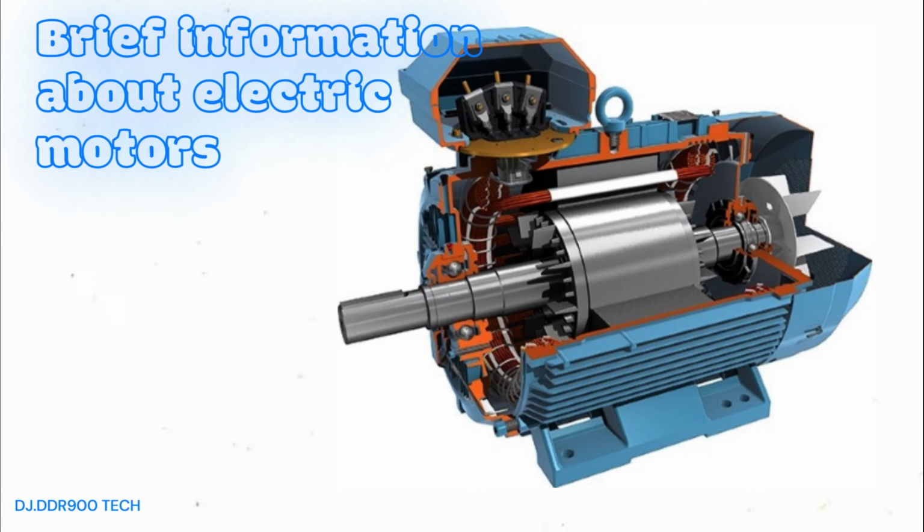The disadvantages of synchronous motors include high price, relatively complex design, difficult start, the need for a constant voltage source, and the complexity of adjusting the speed of rotation and torque on the shaft. All the shortcomings of AC electrical machines can be corrected by installing a soft starter or a frequency converter. The rationale for choosing one or another device is due to economic feasibility and the required characteristics of the electric drive.